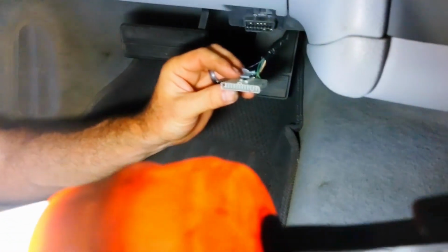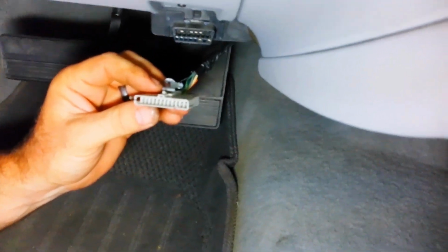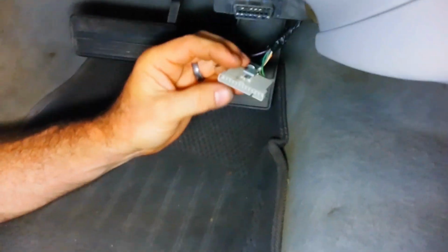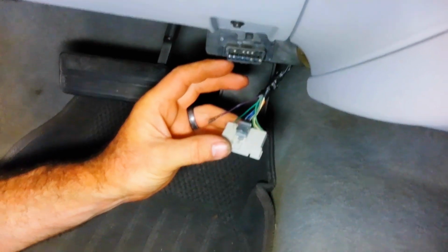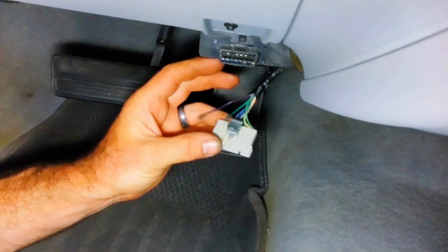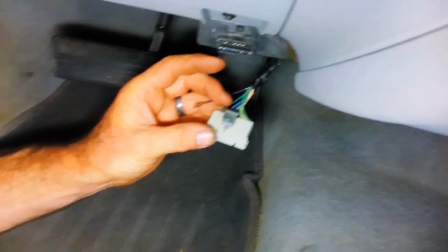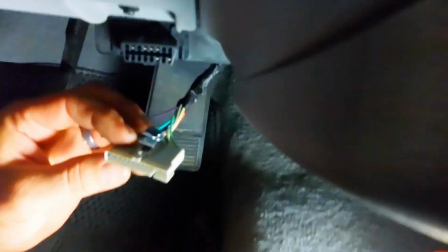Okay guys, this is the splice pack for the network here. It has this little comb in it that just connects them all together. We've removed that comb and we're going to de-pin this. We've got to pull all the pins out of the back. I've got a schematic that shows the locations they go in. This one's actually been de-pinned before and they're not in the stock locations on a couple of them. So we're going to get these all pulled. I'm not sure if you can see what I'm doing here. I'll try to get a little light on it.